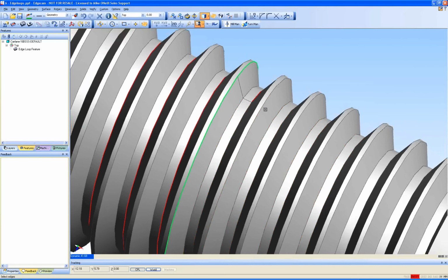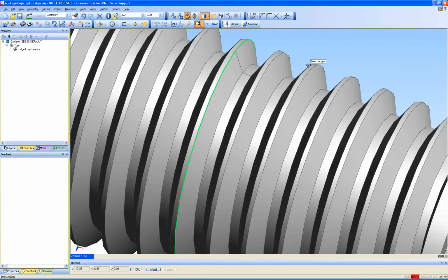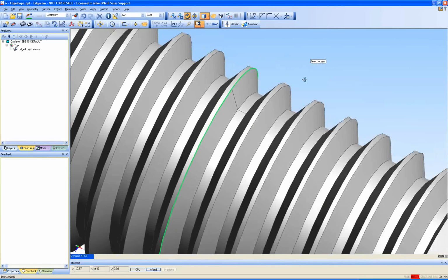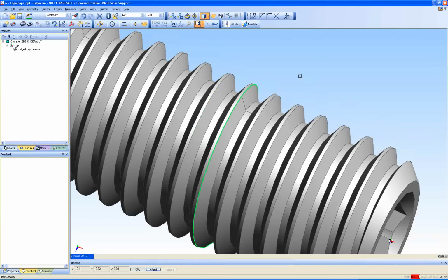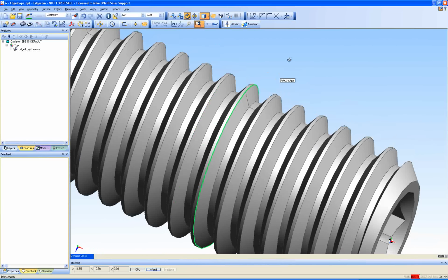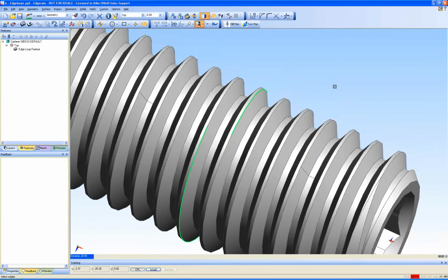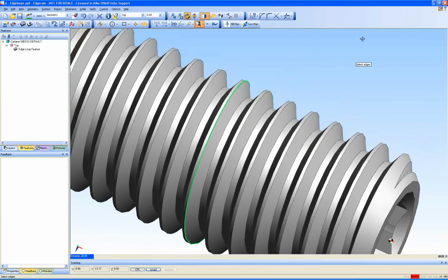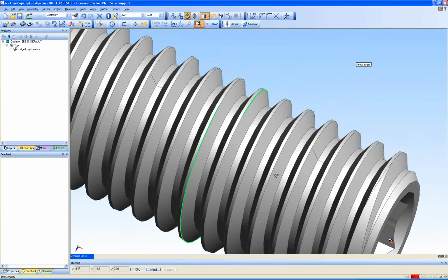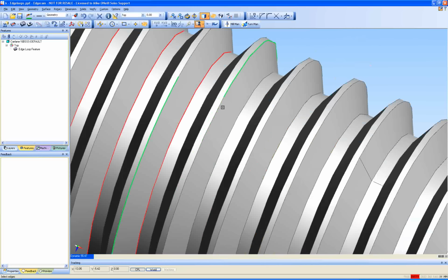And here's another little tip or trick. Obviously I need to rotate the part now around to get to my next area. And when I rotate, the part is free to rotate in all X, Y, Z axes. If I hold down the X on the keyboard, you can see now, very conveniently, it rotates in only one particular direction. So it enables me to digitize this a lot more easily. Hold down that X key and roll again.